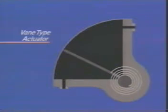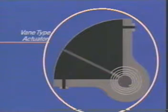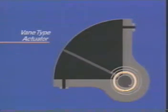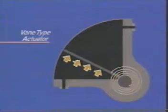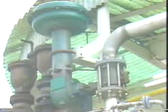One type of actuator that is designed to provide rotary motion is the vane-type actuator. You can see that a vane is enclosed in a casing the shape of a pie. This end of the vane connects to the valve stem and acts as a pivot point. Actuating air applies force on one side of the vane. Opposing force can be provided by a spring or an air spring. This type of actuator is not generally installed when it's necessary to develop high forces. Also, friction at the vane seals can cause problems.